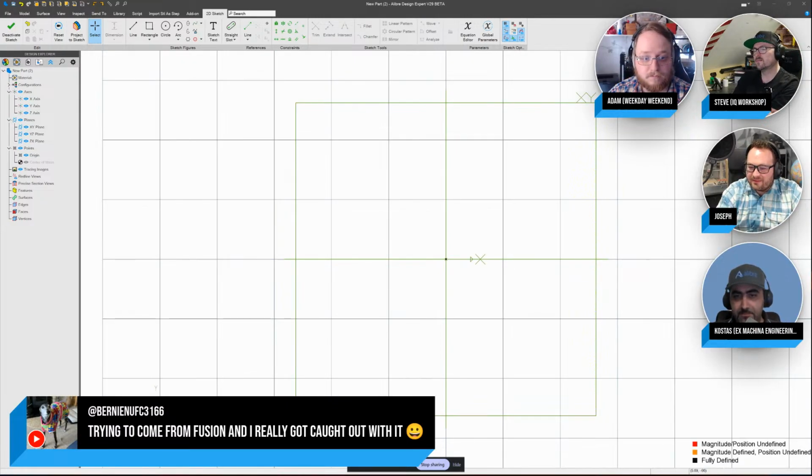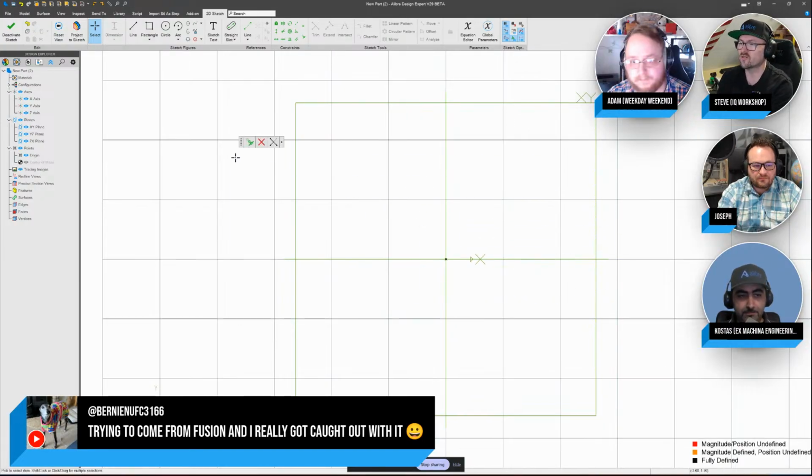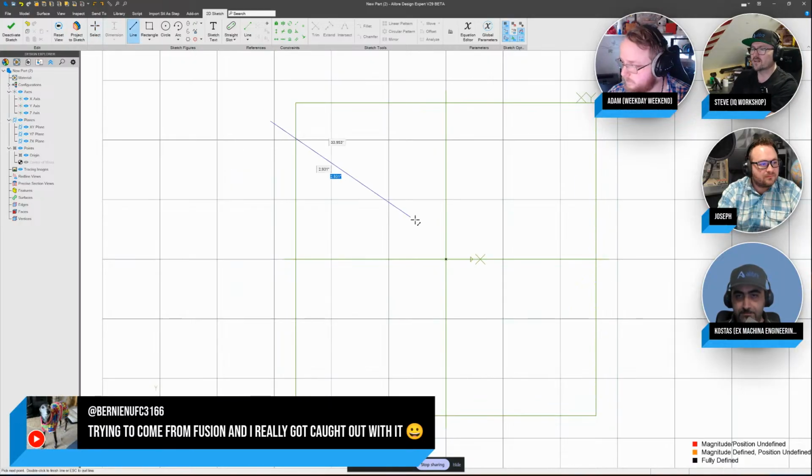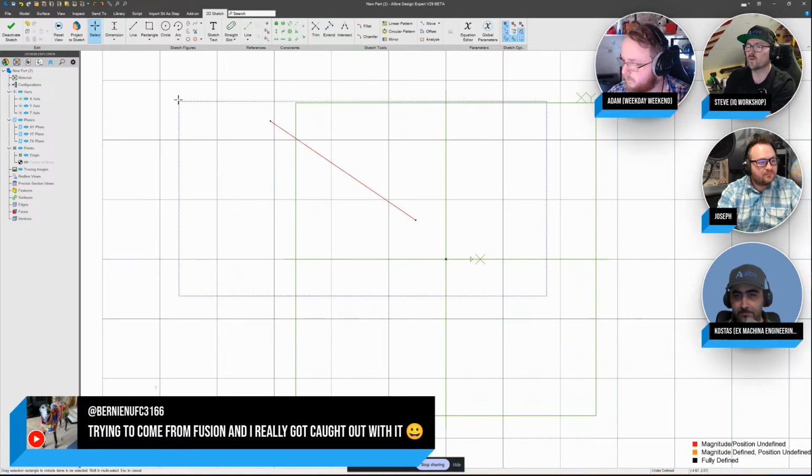Yeah. But still, I like that suggestion. I'm changing the subject again, of that click and drag rectangle. So I want to look into that and see what we can do. Sounds really nice, actually. There's a few other selection options, and I'm potentially going to expose my lack of knowledge here, but clicking and dragging in one direction versus another direction when you're selecting things can often yield a different result. So if you click and drag left, you can select a single line that's within the selection box.